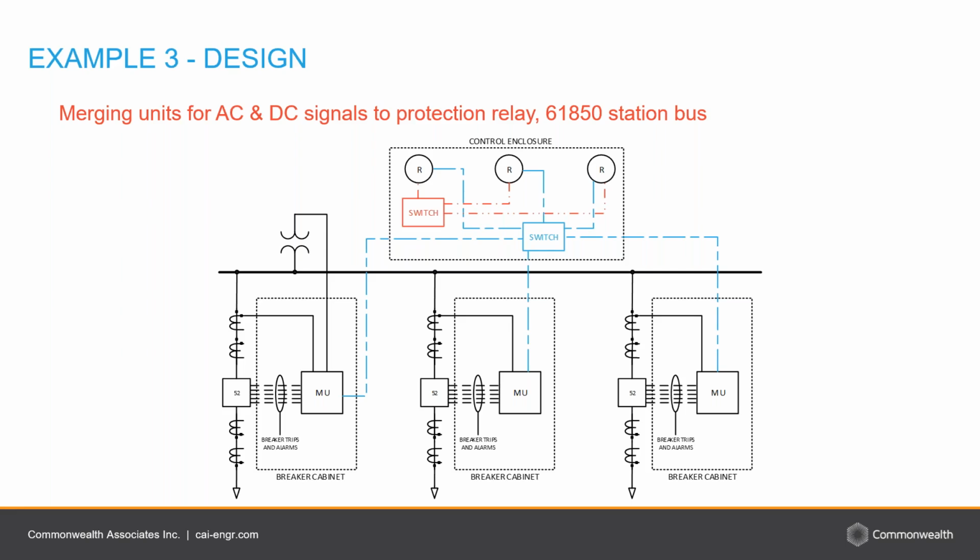Instead of changing multiple wires, say for CT wiring to a bus differential relay, you can reconfigure it on the configuration side and the setting side. So it's not lifting wires anymore, it's changing configuration, which is in large part where that savings comes from, because it's not rewiring, having to take out a screwdriver and move a wire from point A to point B. It's changing a configuration in the relay itself.